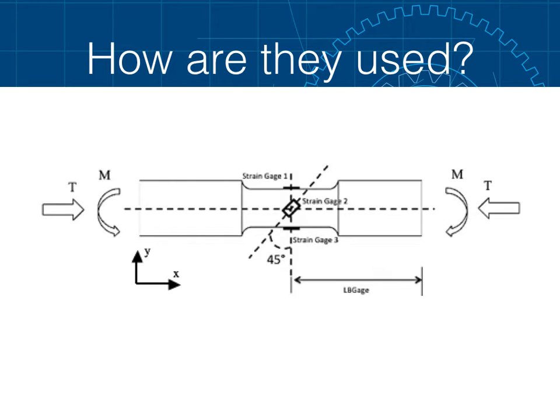Using the measured force, torque, and bending theory, as well as the strain gauge data, one can calculate the Young's modulus as well as the shear modulus. But before we can understand how to obtain material properties from the strain gauges, we must also understand how strain transformation works.